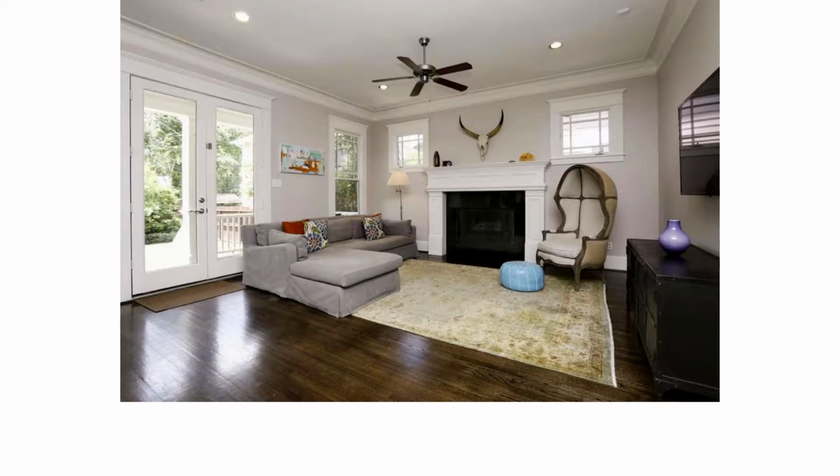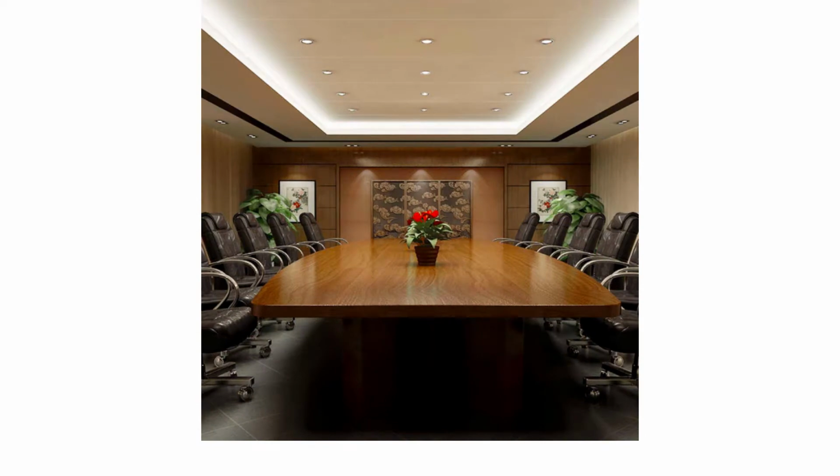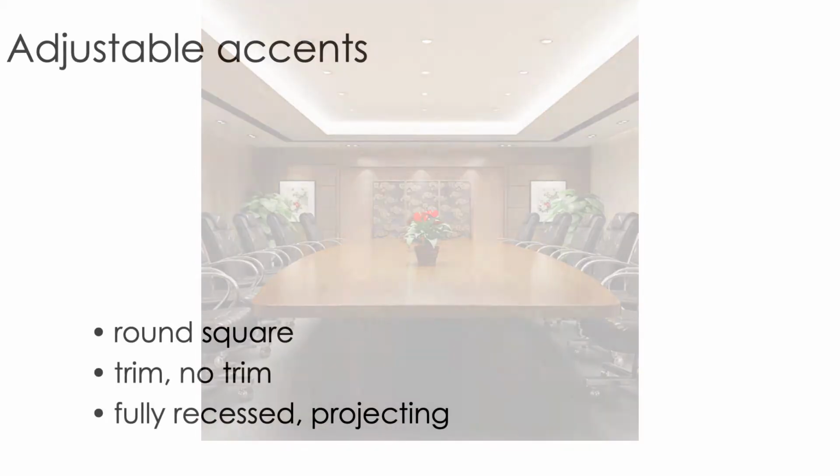Again, you think about how people use the space. In this situation, downlights are fine, but over a bed, not so nice when you go to lie down. And in this case, getting those downlights over the table, I do worry that the center line of the downlights over this table are working fine, but the ones on the outer edges of the table may actually be right on top of people's heads. And that's definitely a no-no. People look funny with lights right above their heads. They may be adjustable, though.